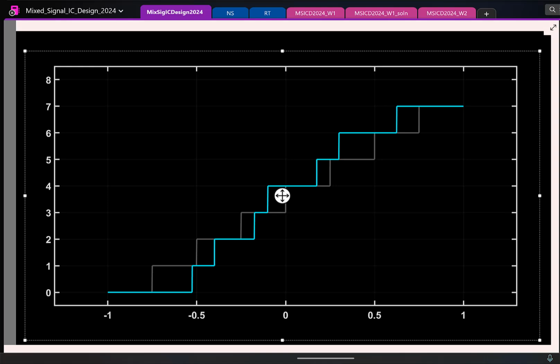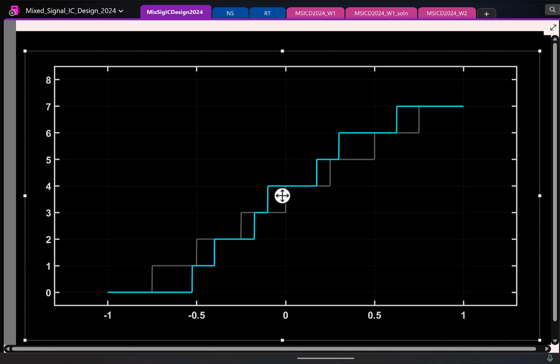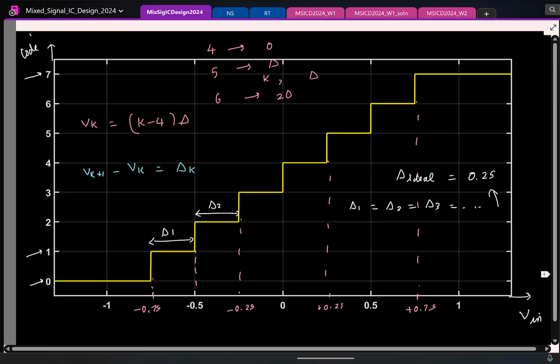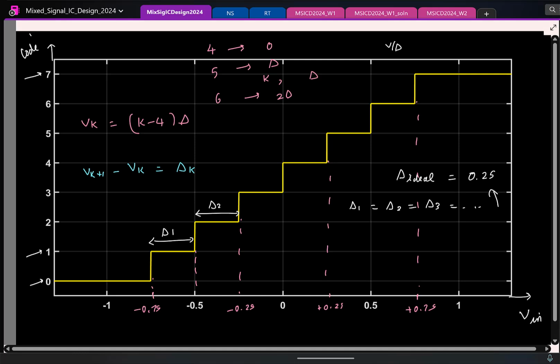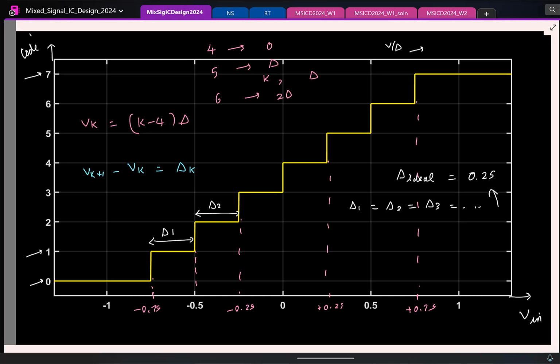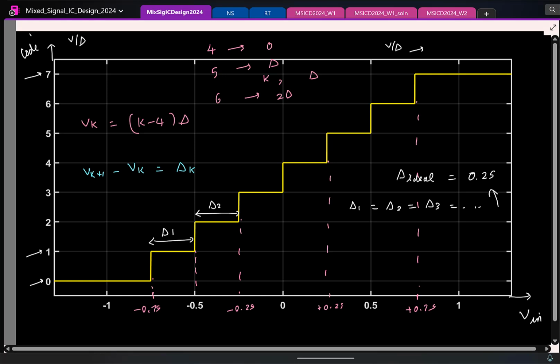Okay. The code is the V output by delta itself, right? Code is not that. When we defined the quantizer, we had an input Y over delta and V over delta. So not that. So here, let us say you get some V over delta. You have, let us say, discrete values for V over delta. I am giving a code. Let us say the lowest one is 0, next one is 1, and so on. Technically you can also plot with V by delta, but this won't be 0, 1, 2, 3. This will be an appropriate value.